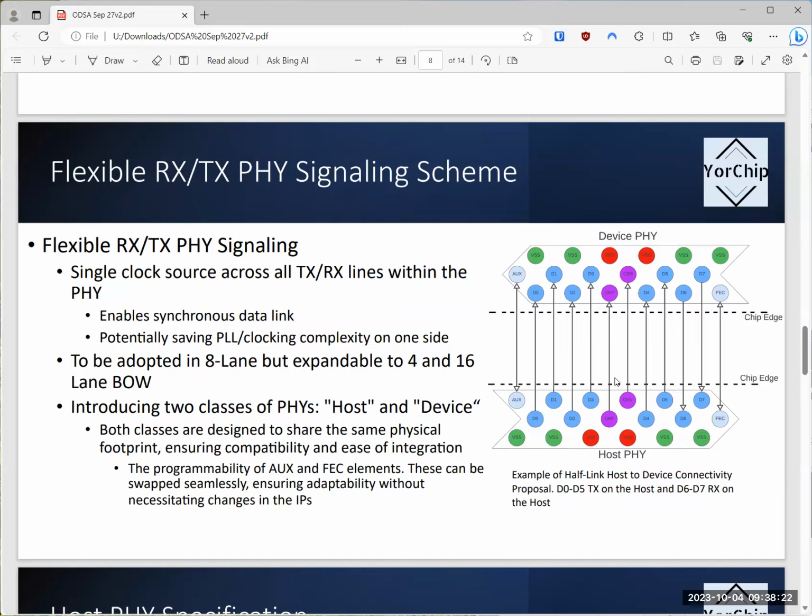I would say you should probably just double up. If you do a by 4 definition, then if you want this PHY to talk to a regular 8-bit slice, it will have to talk to 2 8-bit slices anyway, because one of them will be defined as RX, one of them will be defined as TX. So I would say just follow the same thinking we did for the 8-bit. In this case, I would probably cut bits D0 to D3 and just send on D4 to D7 plus 2 clocks and make that the unit cell of the by 4.